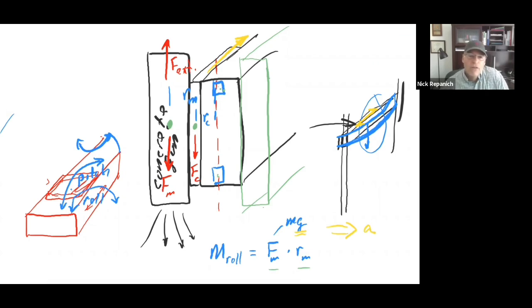So static typically means what happens due to g. Then for the dynamic loading, you ask what happens when I start to accelerate it? Where do you get your acceleration number from in the first place? From your motion profile. How fast do you want this thing to go, and how quickly do you want to get it up to speed? We would need some numbers for that, and from there you would quickly calculate the acceleration rate, and then you have a number that you can put in there for the acceleration.